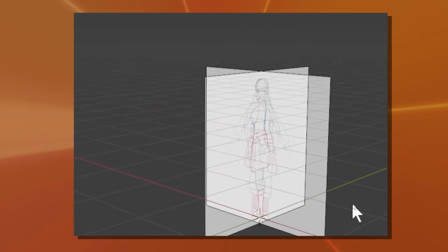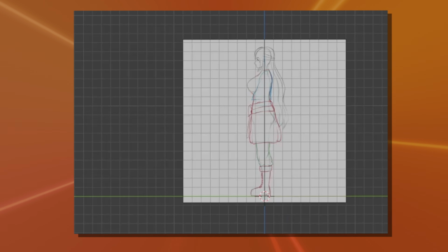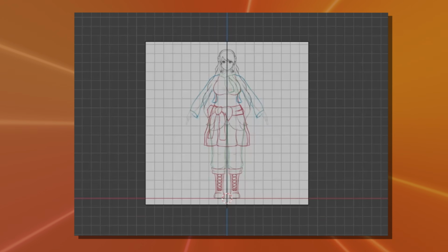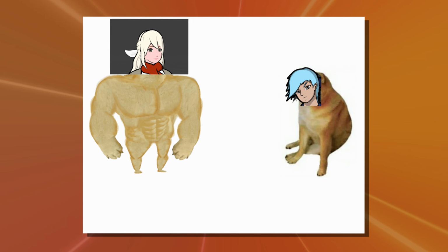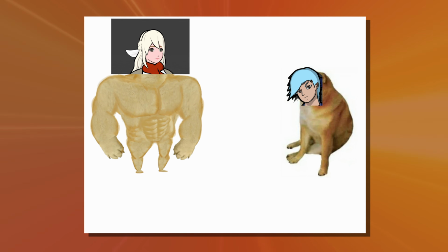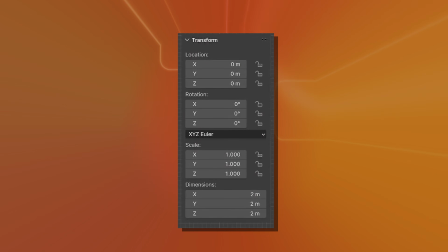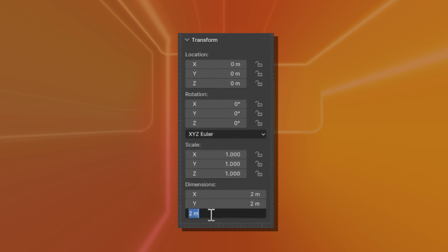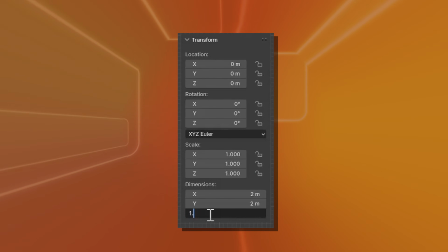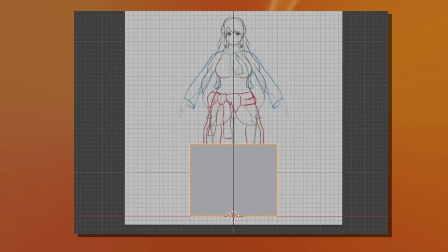Before our reference images are ready to use, I like to use a little trick to get the proper scaling of the character on the reference. It's a pain to realize later on that one of your characters is 10 times bigger or smaller than the rest. Blender does, in fact, have a way to give you actual measurements in real-world units for sizes of 3D models, but it doesn't do this with reference images. Therefore, we'll create a temporary cube, measure that, and then adjust our reference to about the size of the cube.